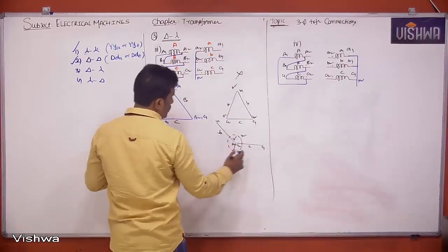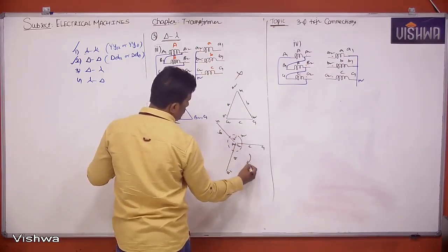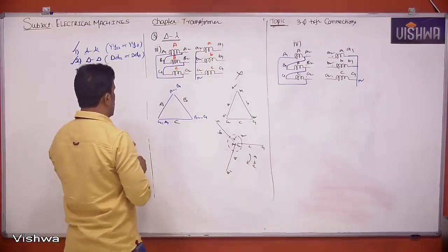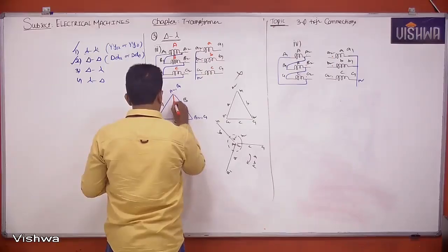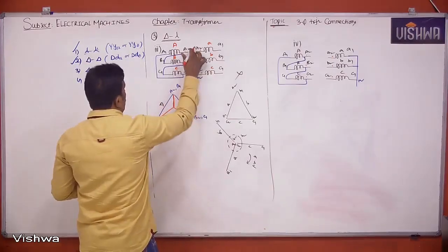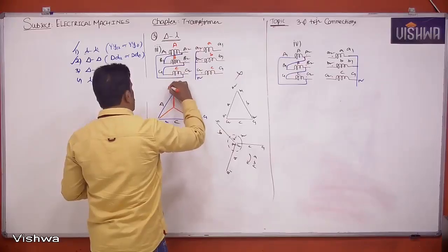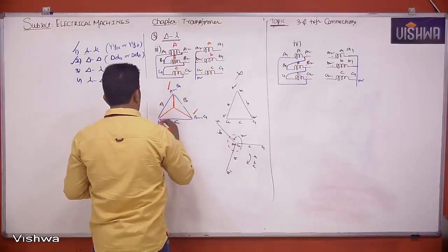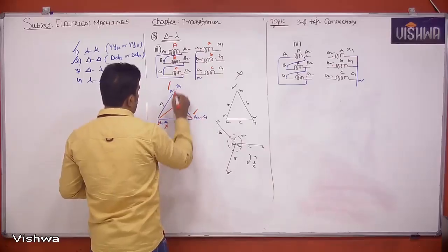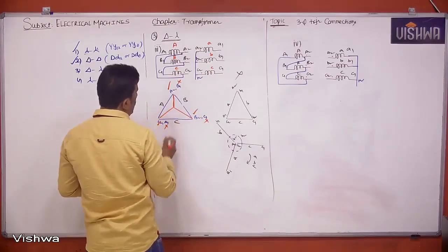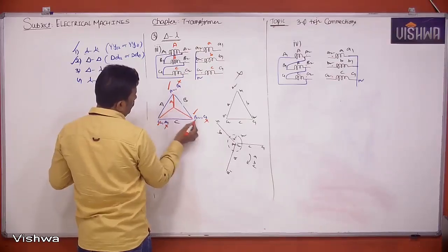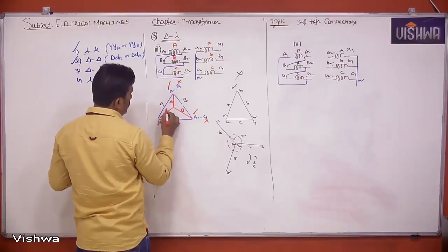Now what is the phase sequence here? ABC is the phase sequence here. And please convert this delta into star equivalent. Before that, I told you one thing you have to do. A2, B2, C2 are connection terminals. You should keep them like this only. A2, B2, C2. And A1, B1, C1 should be struck off. Since it is connected to A2, it becomes capital A. It is connected to B2, it becomes B. Connected to C2, it becomes C.